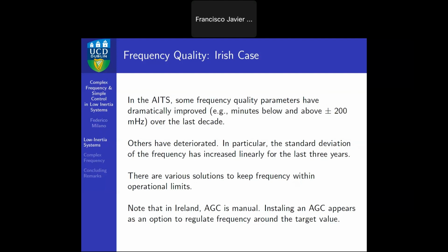Along the last 3-4 years, they have noticed that this increase in the number of periods of high non-synchronous generation share in the system has significantly deteriorated many of these metrics that they have, and they link that specifically with the problem of the inertia.